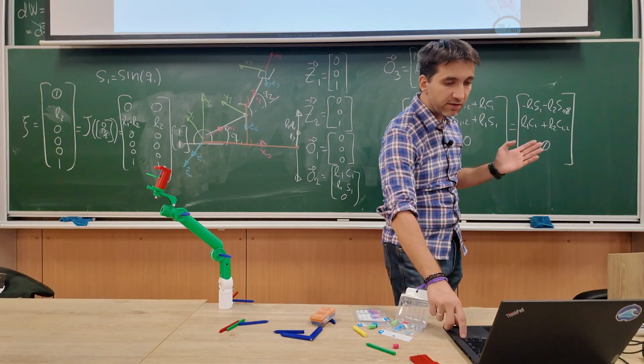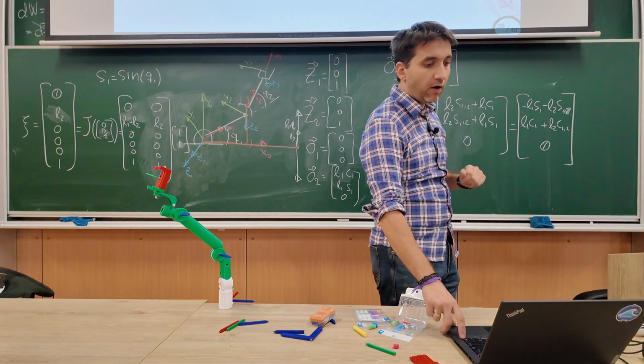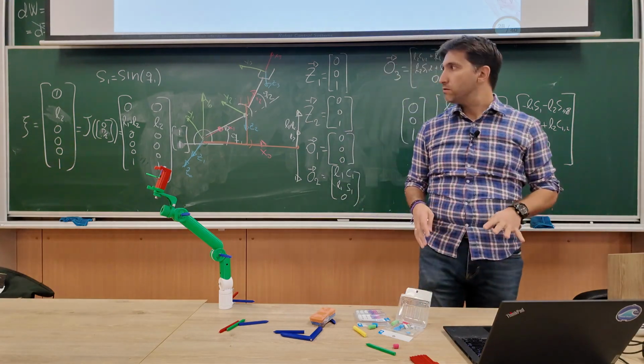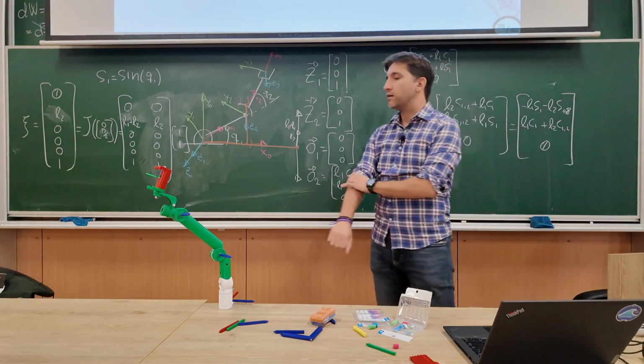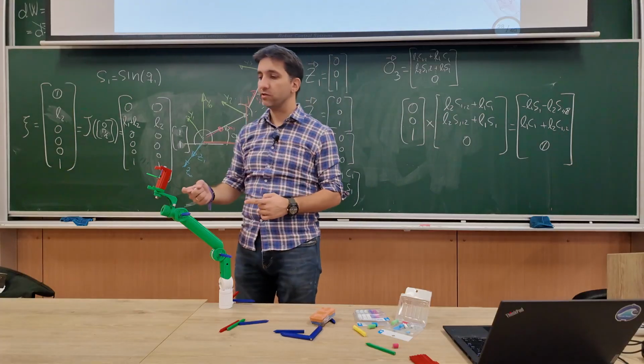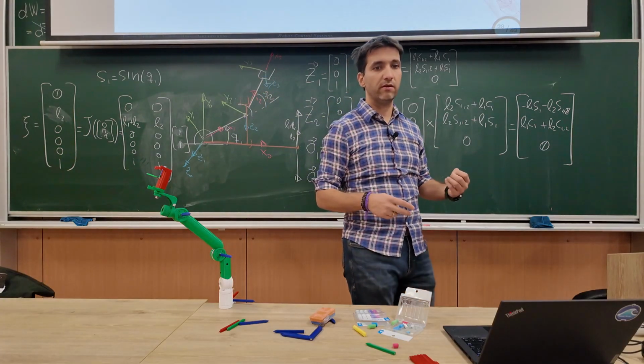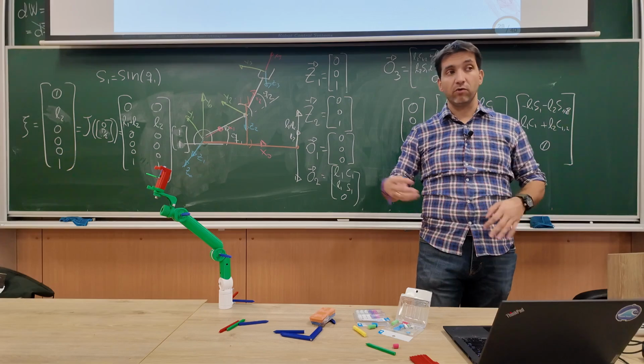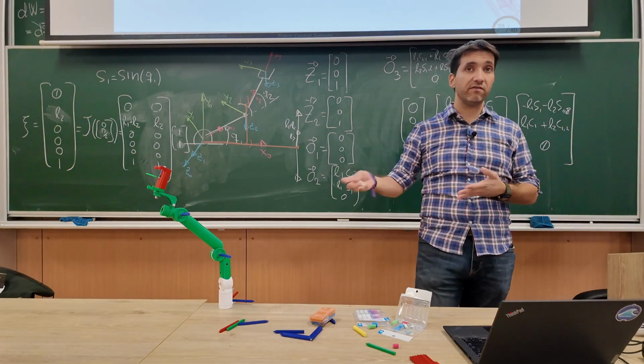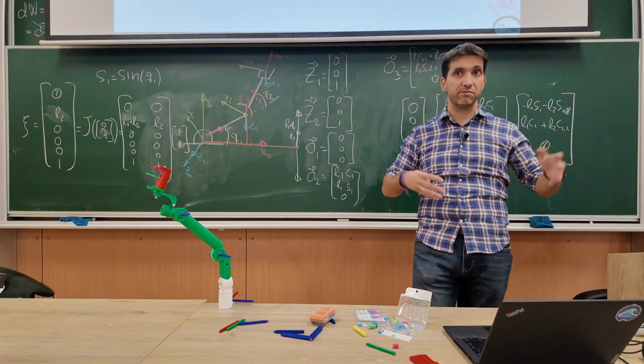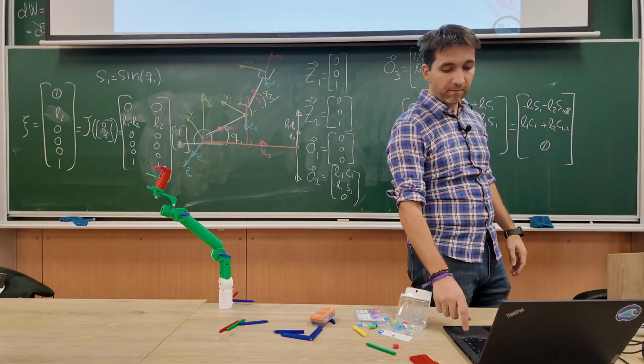What do we need for such a Jacobian? 6 joints, right? Now, there are methods to still calculate end effector velocities for robots with fewer or even more joints. Because if I have 7 joints, then again I have an issue, because I have a 6x7 Jacobian, right?